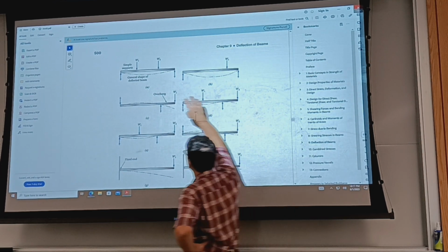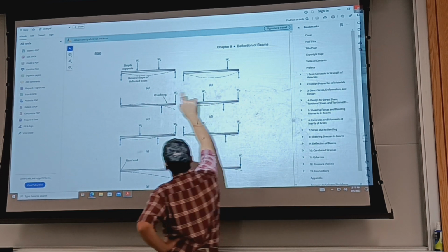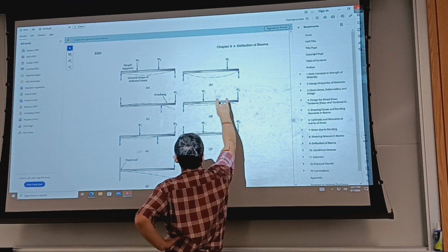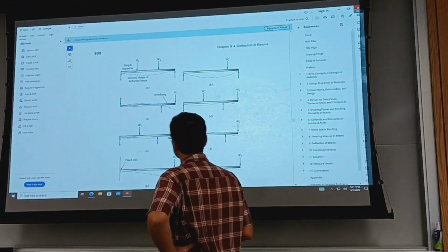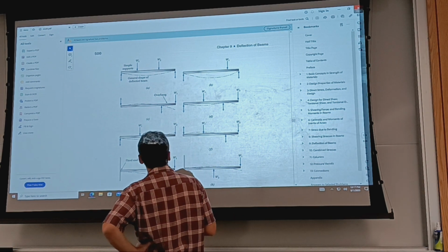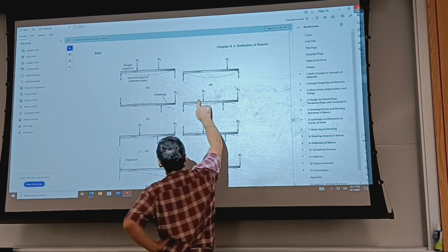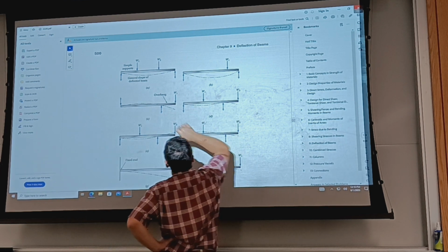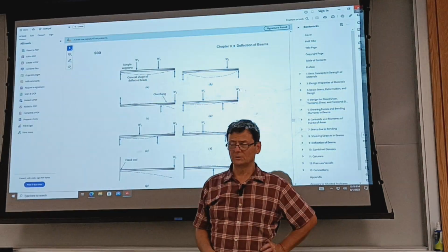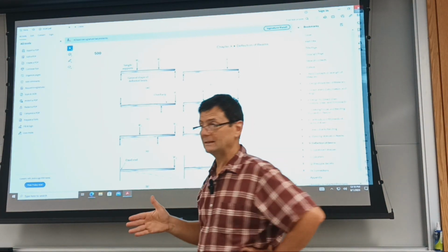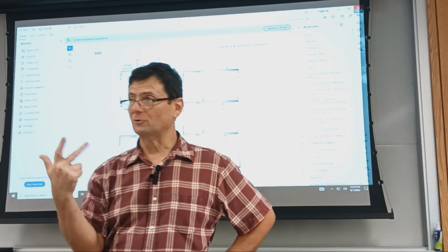And other instances. So we have, as you can see here, just one load. Here I have two loads. You can assume this, and this is something that will be used called principle of superposition. If we have equations that allow us to analyze this instance, and we have another load, we can assume essentially that this case is an overlap of two cases of this type with a single load off from the center, okay? For convenience, I may even mirror, that is, look at the problem from behind if it makes sense.